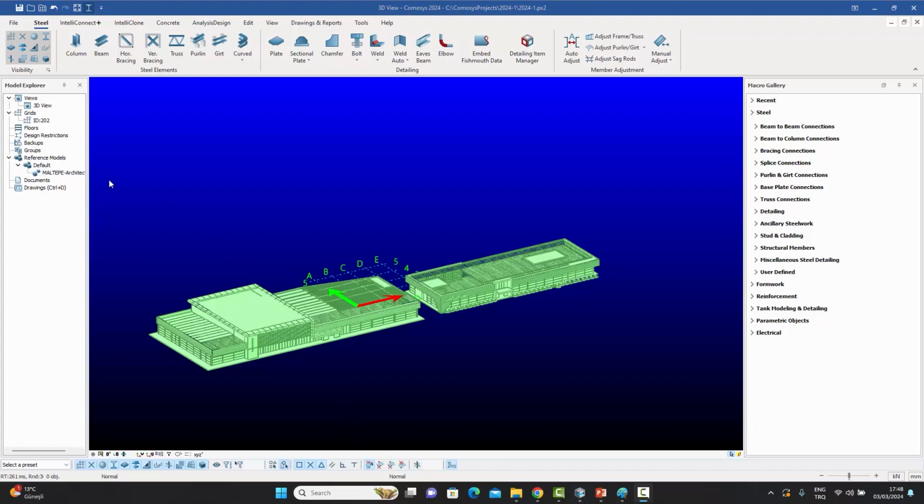So this is the basic advantage we have once the entire reference model is automatically saved under a group. We can show it, we can hide it, we can even update it if the source file changes, and bring it back in. We can delete it, remove it from our list of models, and re-import it later. But the idea is that as long as we don't delete it, we can have as many models as we want under the reference model tab, and we can manage those models by just right clicking them and showing them or hiding them or updating them as we need.